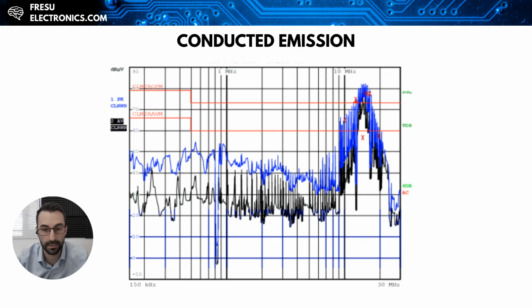Conducted emissions are simply radiated emissions in disguise, and the simple reason for dividing them into conducted and radiated emissions is that it makes testing easier. And the problem with measuring emission below 30 MHz using the same testing methodology as radiated emissions is that the wavelength of the signal can be in the near field region, leading to results that don't match the reality.